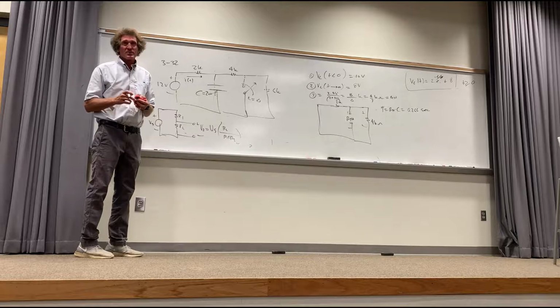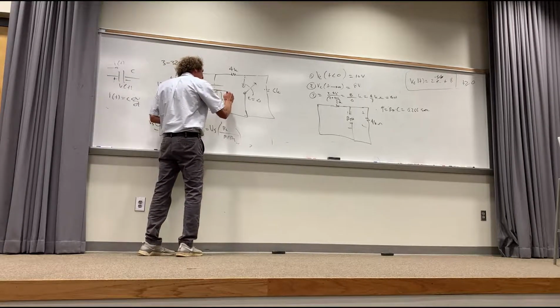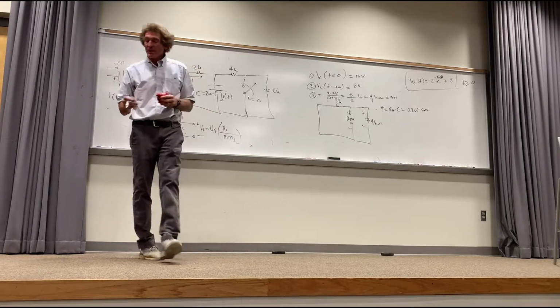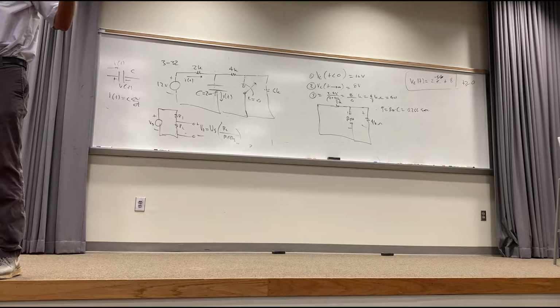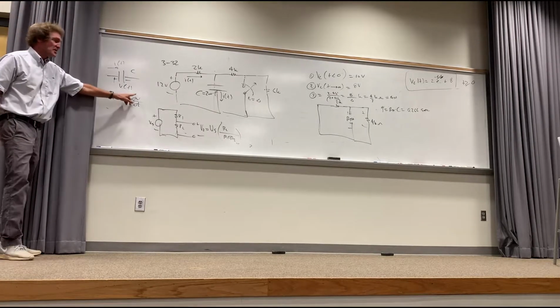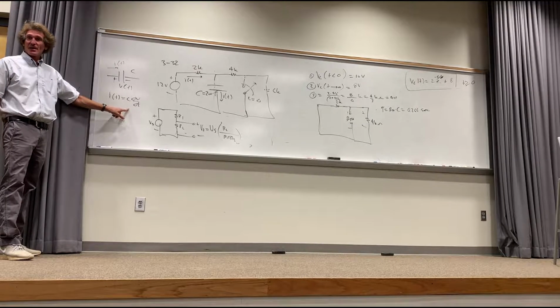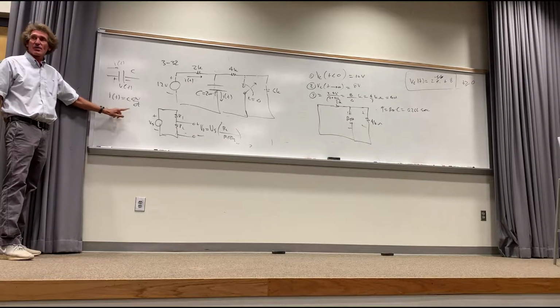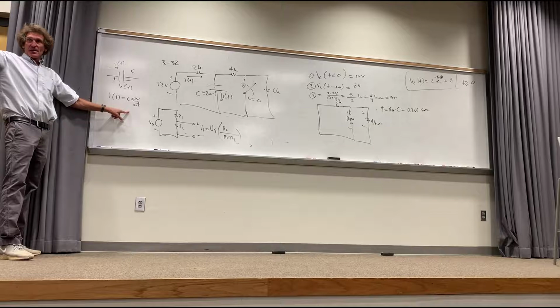This is a really dirty question. How do I get the current there? There's several ways. There's a real easy way. First, you have the voltage there, yes or no? For t greater than 0. Yes, right? What is the current through that capacitor? It's the derivative of the voltage with respect to time times C. You see that? You can go right to this. If you've got the voltage across the capacitor, you have the current just doing that. Are you with me? How many see that?